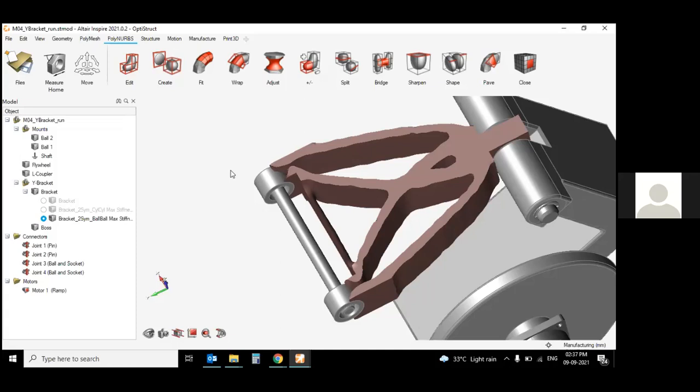Is it manufacturable or not? If it is manufacturable, then check its whole process simulation, whole process analysis using some separate analytical tools. From there, you can get some more idea about the design changes or the die design changes. So from there you have to make the changes in your design and in your component. Then after that, run the detail level simulation again, just to freeze the design for the manufacturing.